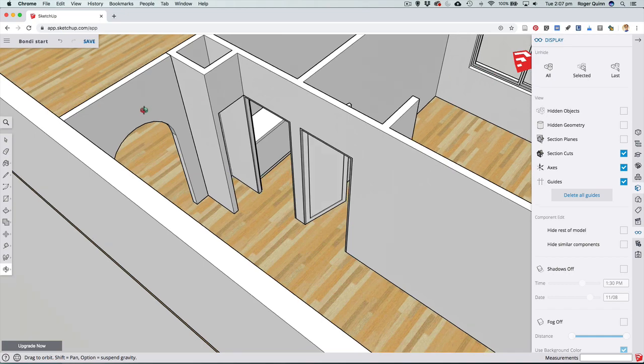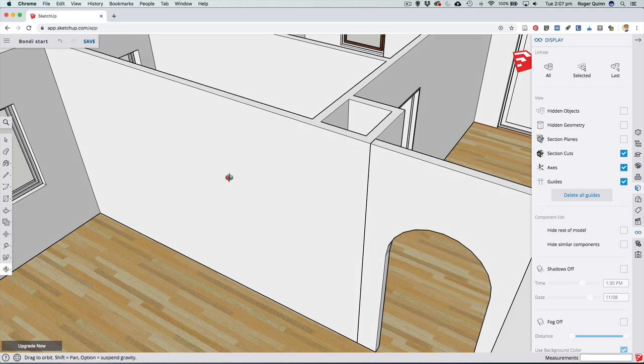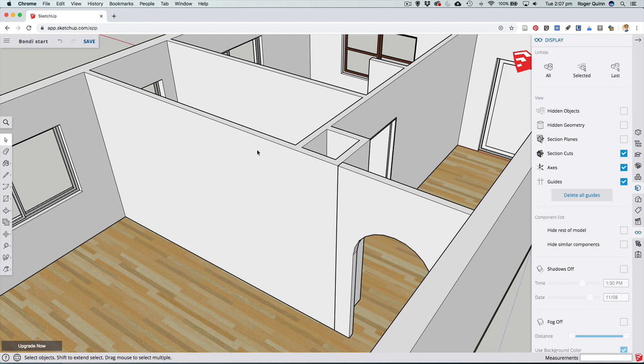As I just said, it really is the same process for making the hole as for the windows. I'll do one very quickly here. I'm going to put a door cavity just here, and I'll quickly show you how you make that frame. Again, I'm trying to find the middle of this space, actually the middle of the internal room, so that the door could arguably go into that. I'll measure across first, which is 3810. 3810 / 2, there's the middle, and I get a guide that lines up.